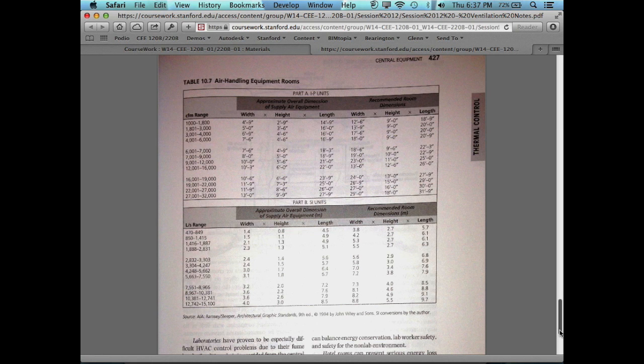Okay. One other application that I just want to let you think about is on a hillside. You can often do this too. Even if you don't want to put it in the building, I could basically put it underground over here. Have it over there. I still need the ductwork going up into the building, and then have some sort of a screen on the top of it. So that's another thing you see an awful lot. It's almost like in a vault of some type. But again, the big thing is it needs exposure somehow to get out to the outside air. And you've got to think about what really makes the most sense: on your ground floor, on your roof, or even possibly external to your building. All of them are possibilities.